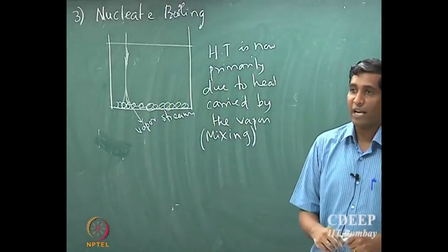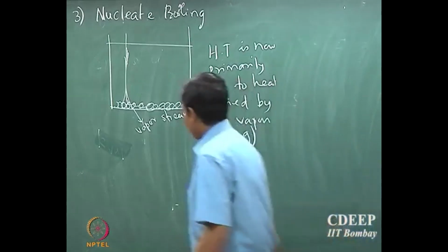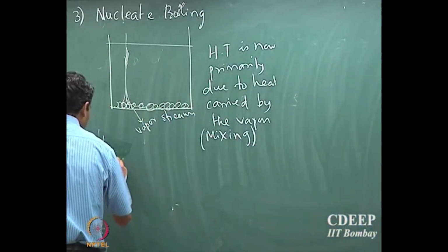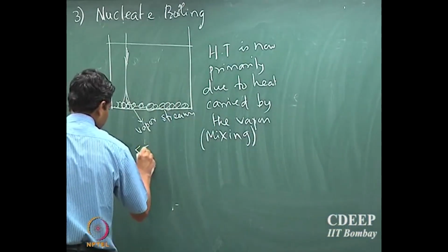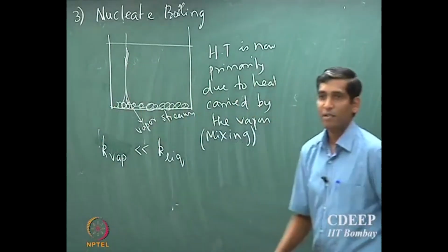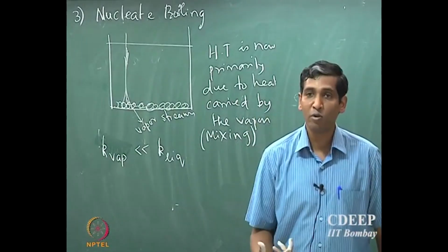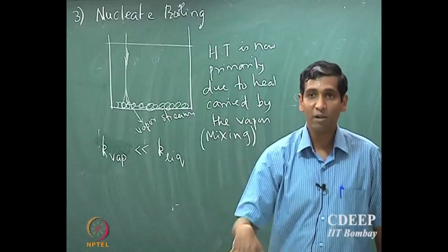In this particular stage, because the conductivity of the vapor is much smaller than the conductivity of the liquid, the net amount of heat that is transported, remember, is going to reduce.